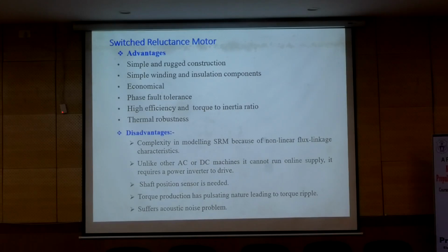And it needs a lot of iterations. For every rotor position, I need to estimate what the flux linkage behavior is with respect to the different rotor positions. And for that, even signal conditioning is required, with sensing feedbacks to sense the position of the rotor. So we need a feedback system, and therefore a shaft position sensor is essential in this case.